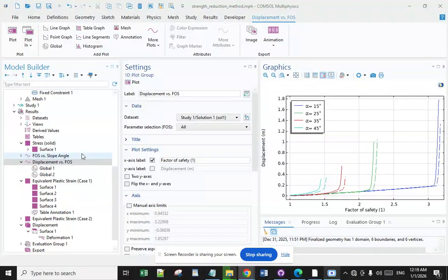With a normal distribution, the tails of measured values may extend well beyond plus and minus 3 standard deviations from the process average. Appreciable portions of one or both tails might extend beyond the specified tolerance. The process capability of systems, materials, and products needs to be compatible with the specified engineering tolerances.